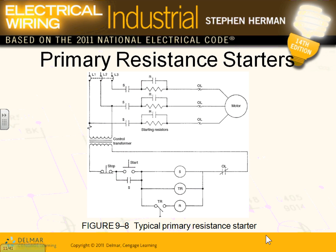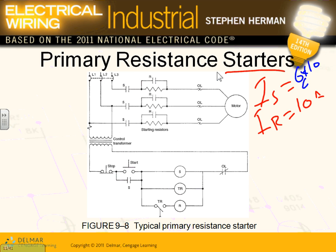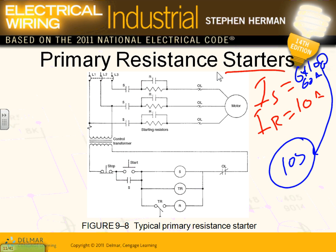Because of all of this, guys, they want to reduce the starting current to reduce the starting torque. Here's one method of reducing the starting current. This is the I start. Remember that I start? If I run on a motor is 10 amps, I start is usually, let's say, 6 times this. 6 times 10 gets you 60 amps, for only about 10 seconds. That's not a whole lot of time. For 6 to 10 seconds, you will suck 60 amps to start a 10 amp motor. Who cares? Mechanical stress, electrical stress.